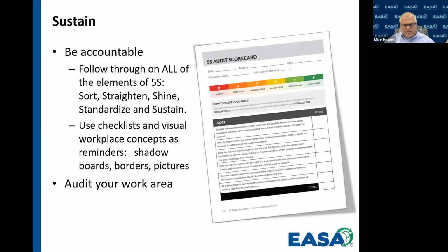A lot of larger organizations have personnel that kind of do this stuff all day. So they might use these 5S audit scorecards. The same kind of tool. It doesn't have to be an independent audit. You can use it in your own workplace or your own workstation, but it gives some kind of indicator of what needs to be checked, just like we use check sheets when we go through a motor inspection. Not because we don't know the steps, but it helps us not miss anything and just know that we've touched all the areas we were supposed to.